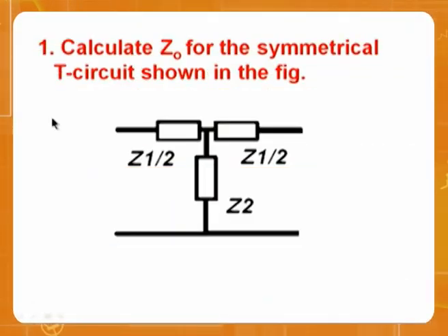Sometimes we call it iterative impedance, or the impedance seen at the ports, the load impedance. If you terminate this impedance with the same impedance, the impedances will be equal and then maximum power is transferred. Now let me take an illustration by taking a problem.